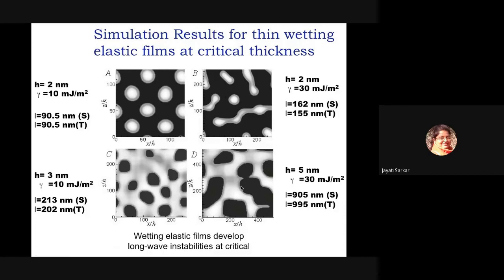So basically what it tells is that the rheology gets marred. It is only the geometrical configuration that dictates what type of instabilities will be formed. So even in elastic films, there are certain parameters that we have to look into. If the surface tension is very high, then we will definitely have long wavelengths. Surface tension effects will come into play, and even in elastic films we will get long wave. Whereas if we cast a wetting film, then it is not possible to get short wave even in elastic films. It will again be long wave, because of the morphology or the configuration of the film.